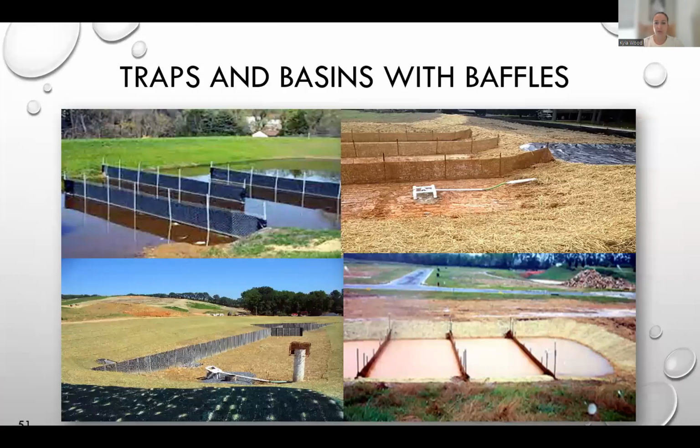So one thing that we see a lot that's really beneficial, especially if we have fine particulate, is to use baffles in the basins, especially if they have things like the core material that they're made out of, because they can capture flock. So that can be a really great way to capture flocculated particulate as well. We like to have every application have a 20-second reaction that creates giant flocculated particles that immediately settle out of the water. That's not always the case.